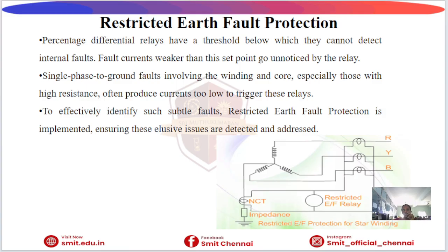Next, restricted earth fault protection. This protection detects earth faults inside the transformer. It is more sensitive than differential protection. It uses CTs and a neutral CT on the transformer, and it is also useful for low fault current conditions.